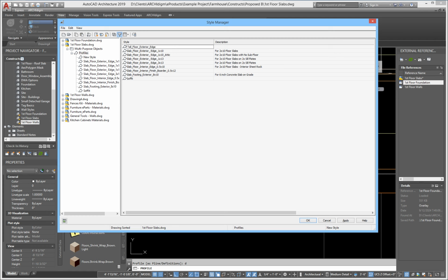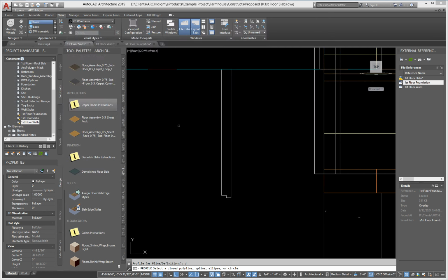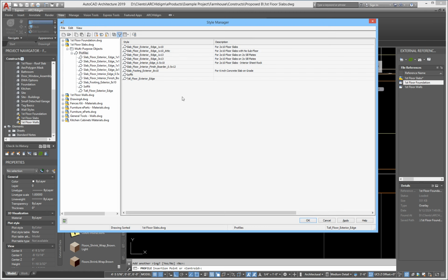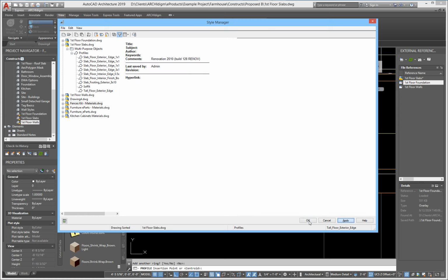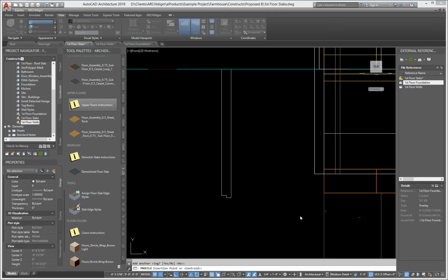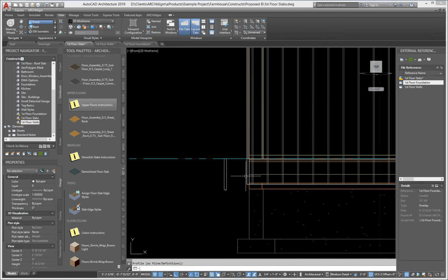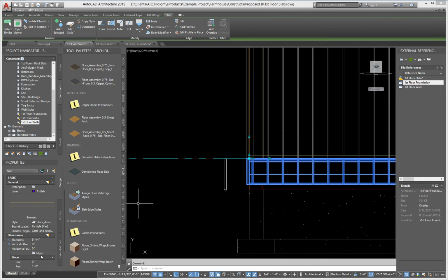Edge. If I had paid attention to the dimensions, I would like to put the dimensions in it. You can see the ones we've made have dimensions on them. But now I'll go ahead and set from. Okay, and then you'll want to do the left corner, the upper left corner. So I'll snap to that upper left corner and hit apply and OK. And now I'll go ahead and I'll pick the slab.